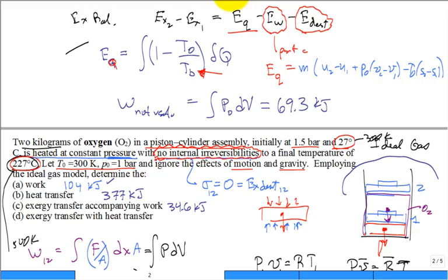Internal energies we've talked about, but we haven't talked about the changes in the entropy for an ideal gas, the oxygen, have we? How do I get the change in S for the oxygen? S2 minus S1 is needed right there. How do I calculate that? Well, S2 minus S1 is equal to S2 naught minus S1 naught minus R natural log of P2 over P1. True or false?